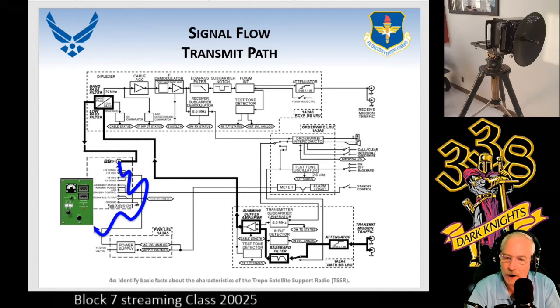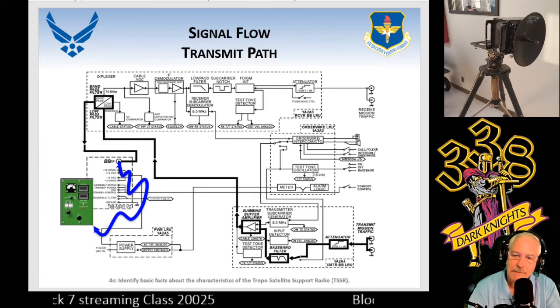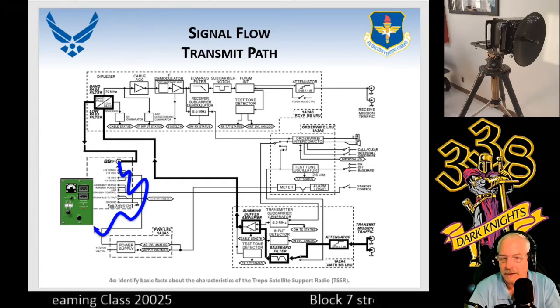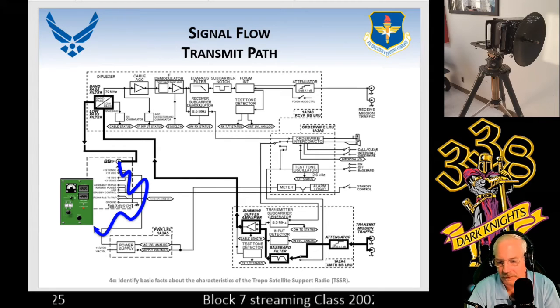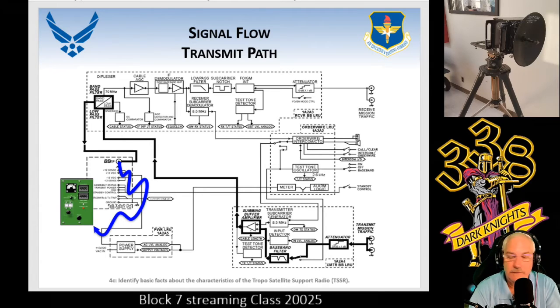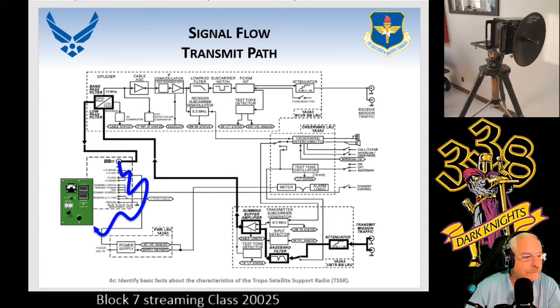You have the Orderwire on that signal, but in the same context, you have 70 megahertz going the opposite way. So it is a two-way path on a single cable, and they don't interfere with each other. Think about it, 70 megahertz versus just from 72K to, let's just say 8.5 meg. All right? So it's not going to interfere with it, so you basically have a two-way street here.